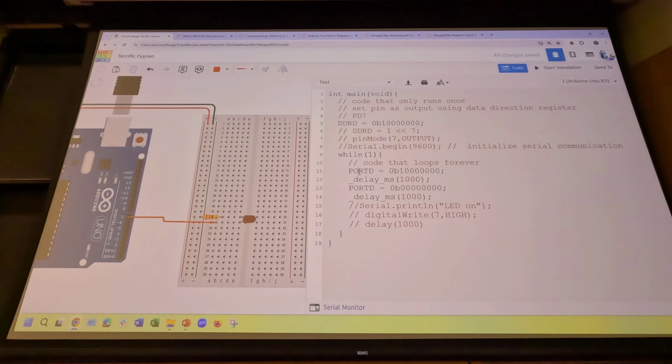Again, the motivation here being ultimately you're going to need at least 4 of these for your robot, right? You have 2 motors, an H-bridge for each. Each H-bridge has 2 inputs. That means you're going to need to control 4 outputs for full directional steering of your robot.